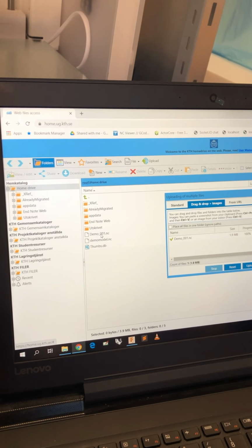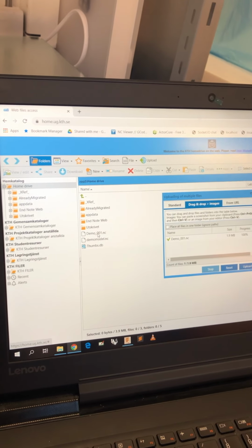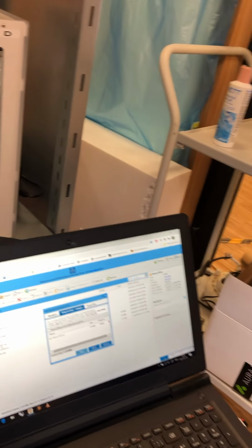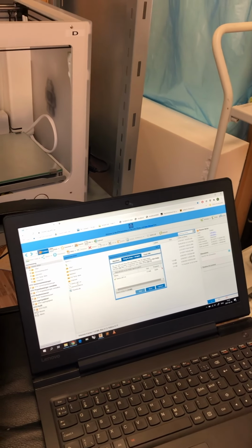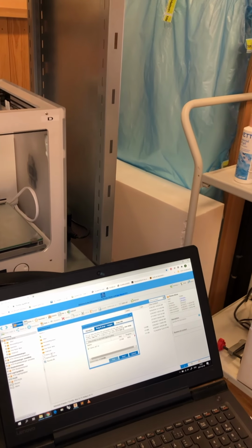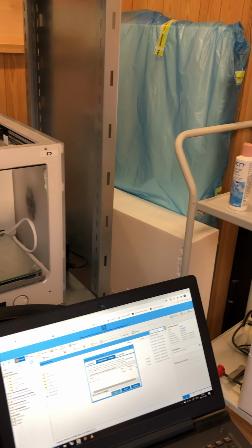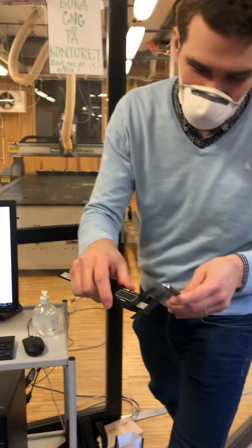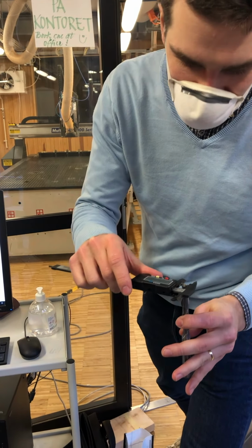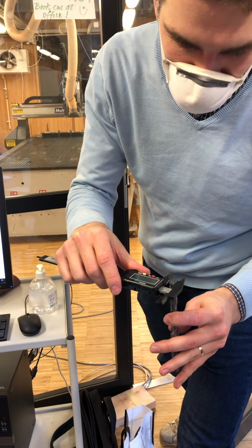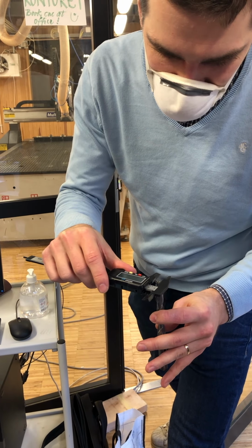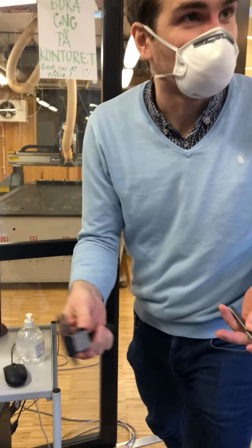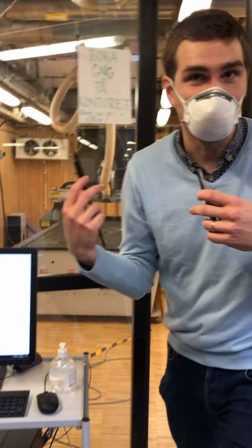Now it's in its final phase of the warm-up, so now it's 18,000 RPM. That's a lot of RPMs, and it's 2 minutes left on it. So yes, and one can make sure that this is 12 millimeters in diameter. I think we have already done that, so that not only the tool number is correct, but also the dimensions of it. So just to make sure that it's 12 millimeters. And this seems to be about 11.5, which is within tolerance. That's of course depending on your tolerance on your project.